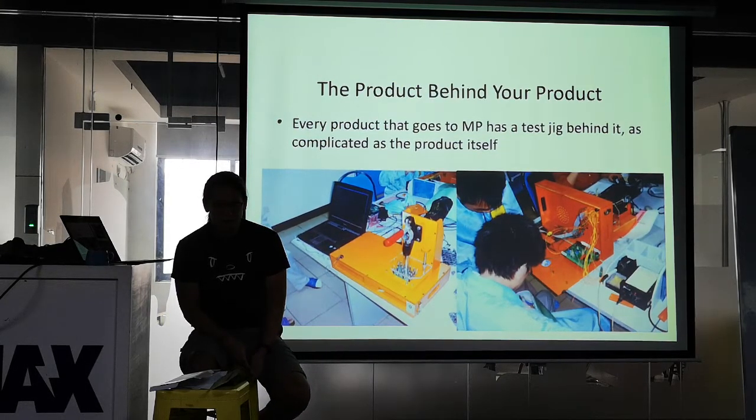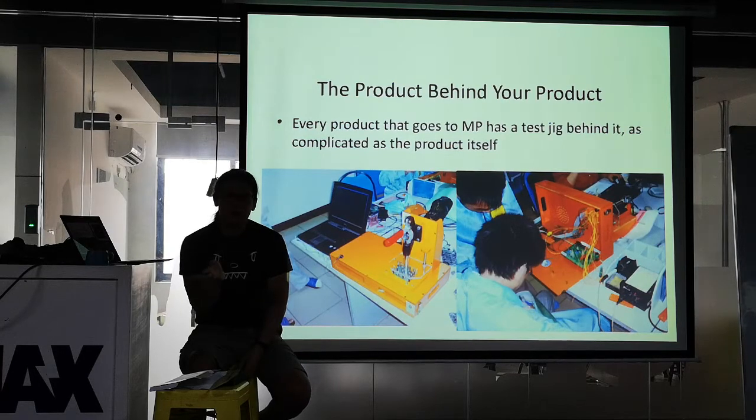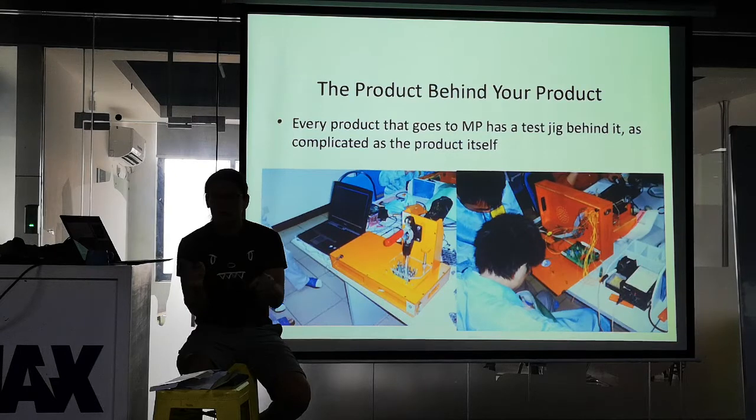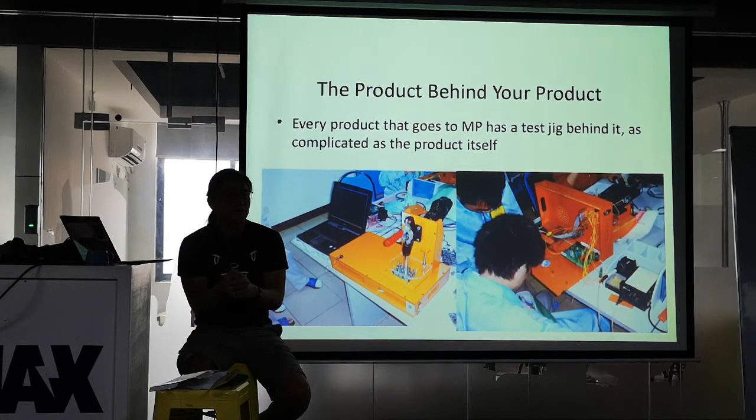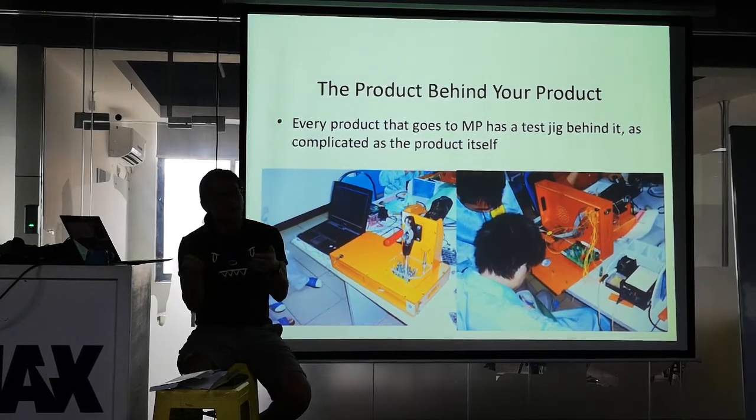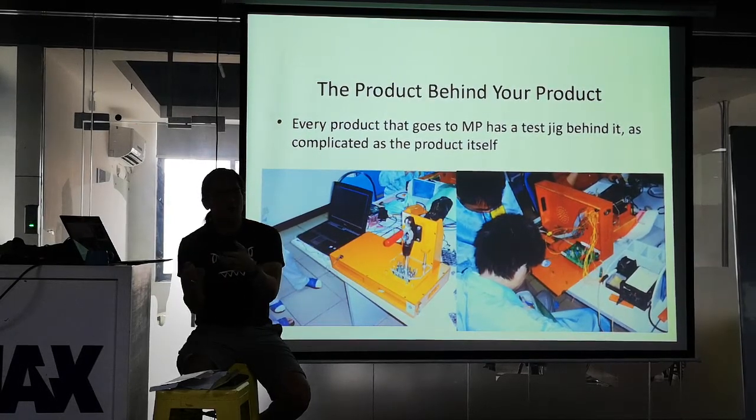There are some open source testing frameworks. Sean in particular, who's no longer here with us today, wrote one called Xclave. It's written in Rust. The idea is that as you get your PCB back, you'll say, does the LED work? Okay, fine. I'm going to write a little bash script that lights up the LED, or does the accelerometer work? I'm going to run some I2C command that checks the ID, whatever it is.